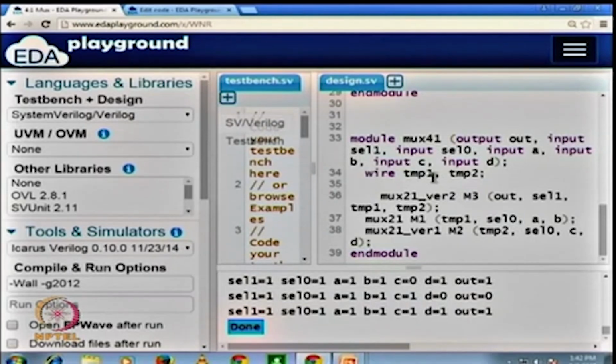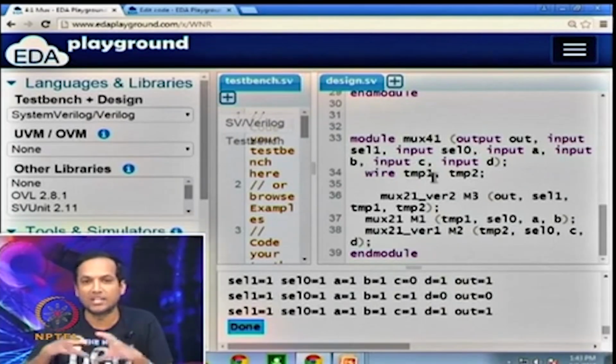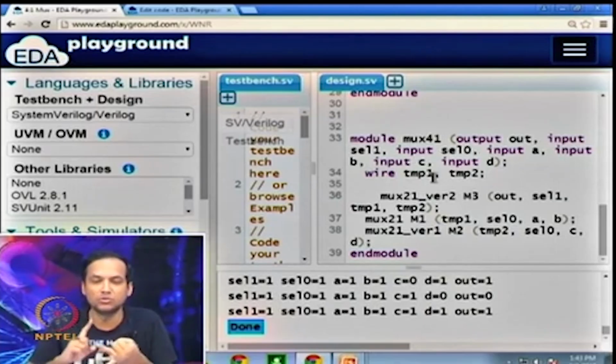So what we have done from week 1 to week 5 in terms of Verilog is that we have seen how to write basic modules, all the way up to the 4 fundamental ways in which you can write a design. You can instantiate, you can use primitives, you can use always block, and you can use assign statement. In fact, when you instantiate, the underlying model should use one of the three: either primitives, or always blocks, or assign statements. So the instantiation is just a meta thing, but the underlying things are you can use assign statements, always blocks, or primitives directly.